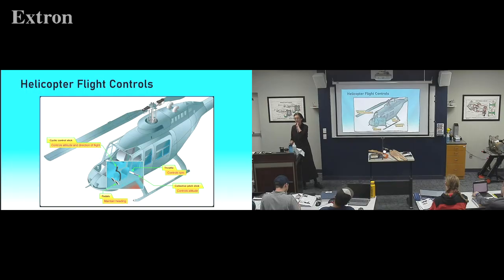I'm just curious, if that system had zero friction, would it still want to spin? You still have torque happening. If you get up to a certain speed, your horizontal stabilizer will take the job of the tail rotor. But once you get below a certain speed, the torque will start taking over again. Because there are situations where your tail rotor stops working, and you have to figure out how to land through that.